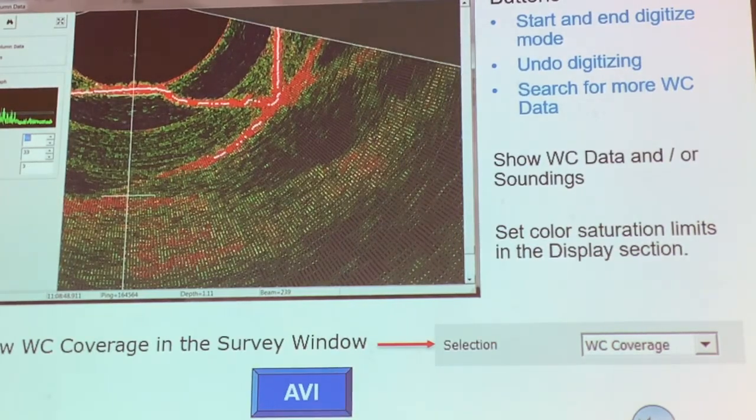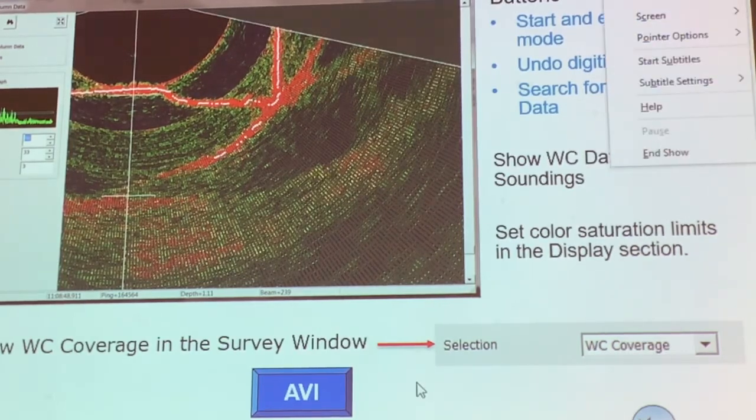Yeah, you can see sediment plume. If you have suspended sediment, it will also show inside water column data. But like I was saying yesterday, when you do water column, you need a very big hard drive because it's a lot of data. Every 1 minute is 2 GB. So if you do 1 hour, it can take 1-2 computers to finish. So I'll just show you the water column video.